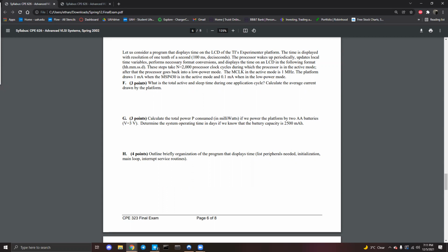It was given to us in a roundabout manner by telling us it's 2000 clock cycles active. You can just convert that to time via the main clock. And then you just need to know how much current it consumes during either period, and how to calculate a weighted average, which might be a big ask because no one does that manually.